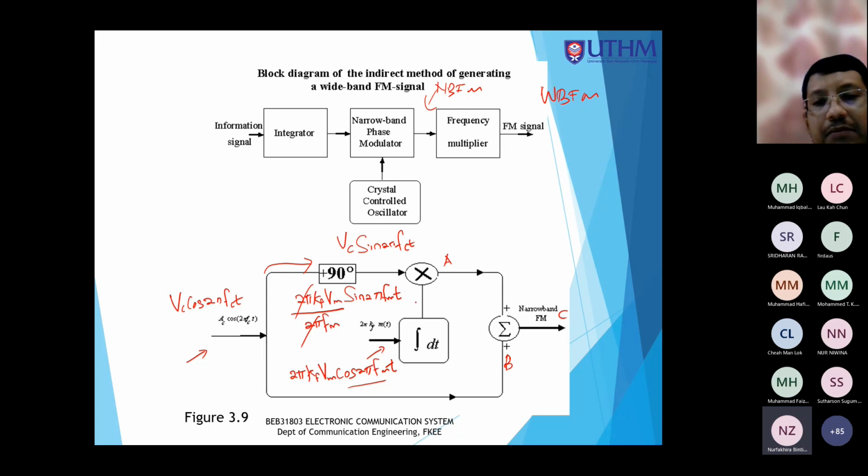So this is actually equal to beta, so that you can put just beta sine 2π fm t. You can put beta f or you can put beta, it's up to you, no problem, as long as we know that it is a beta parameter, the modulation index.